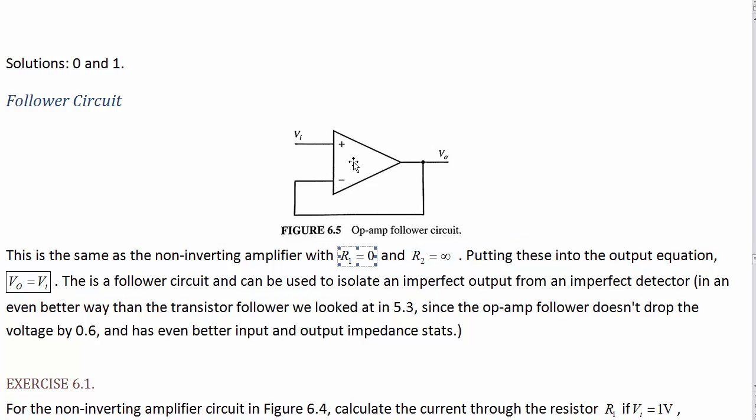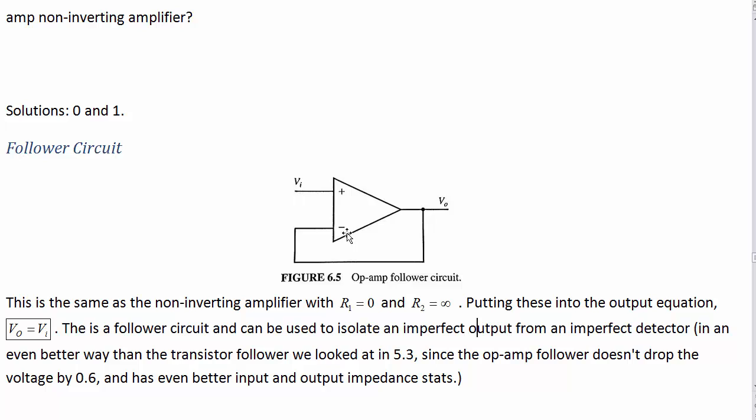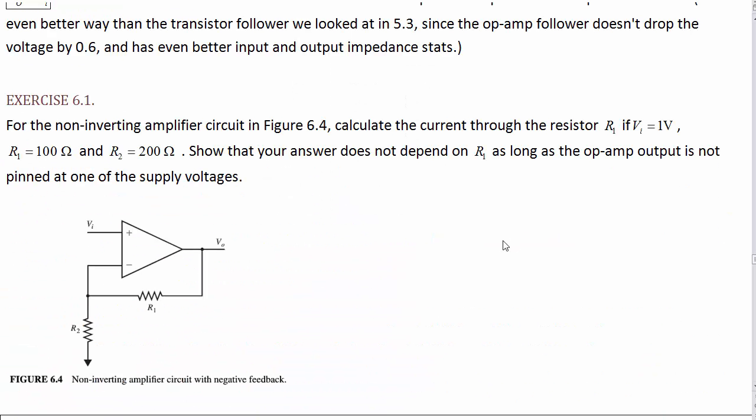So now we get the op-amp's magical properties. This circuit gives us infinite input impedance and 0 output impedance. So it'll maintain this voltage no matter how much current we're trying to draw out of it, and we won't be able to push any current into it. So that means this entire circuit is keeping the op-amp properties of infinite input impedance and 0 output impedance.